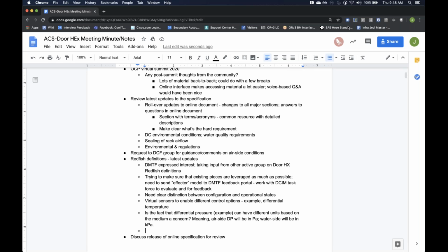And then we need to figure out how to do this on the configuration side, to say, I've got some number of inputs, and those are mapped to some functionality. And you probably also have the ability to name the input. Right. Oh yeah, naming the inputs, that stuff's easy. So you would go in and configure input number 1 to a normally open condition and name it as door open or door closed or something like that. And then when you go into the operational state, you don't really see the micro switch. All you see is the door state. Exactly.